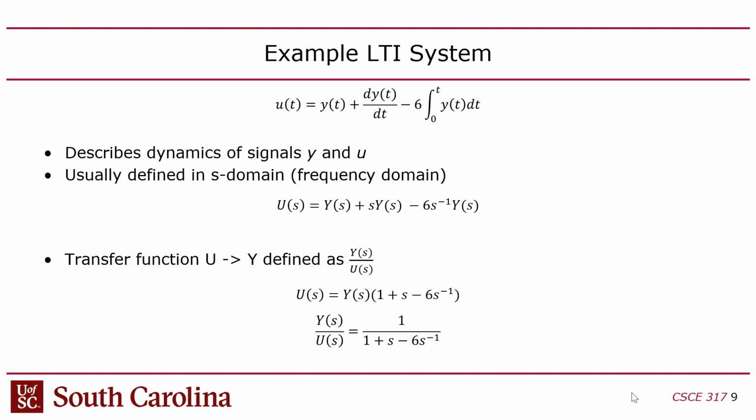Okay, so that's what they often call the poles being in the left-hand plane of a plot, where you think of a complex plot where the horizontal axis is the real part and the vertical axis is the imaginary part. As long as all the poles are in the left-hand part of that plot, then the transfer function is stable.